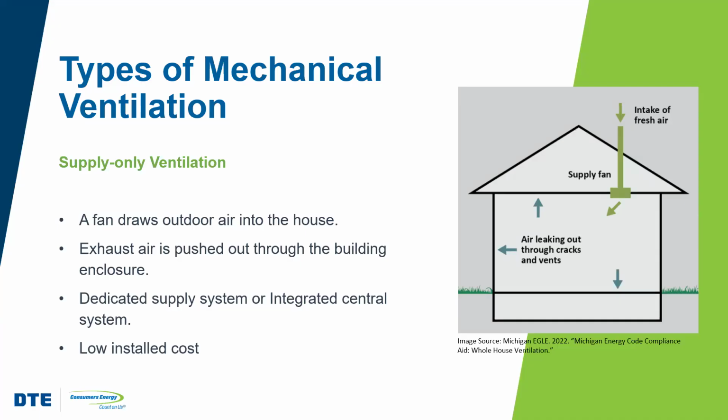Here you may or may not be conditioning that air that you're bringing in. Oftentimes, you will certainly be able to filter that air. Sometimes the supply fan may be connected to the central fan. It can be connected to the central air handler or furnace in the home if it's a forced air system.